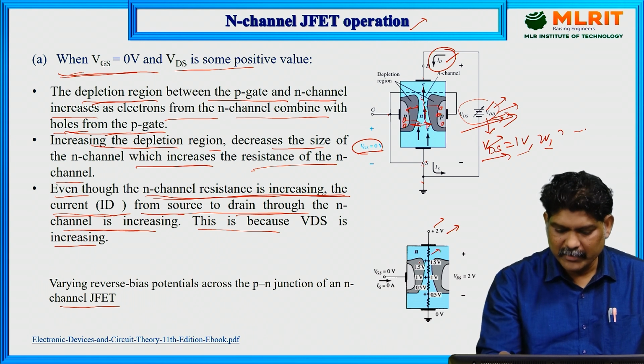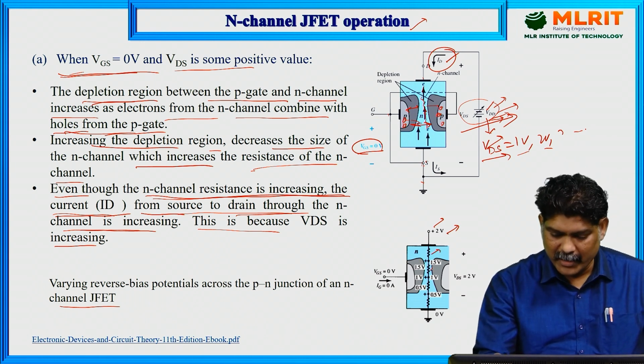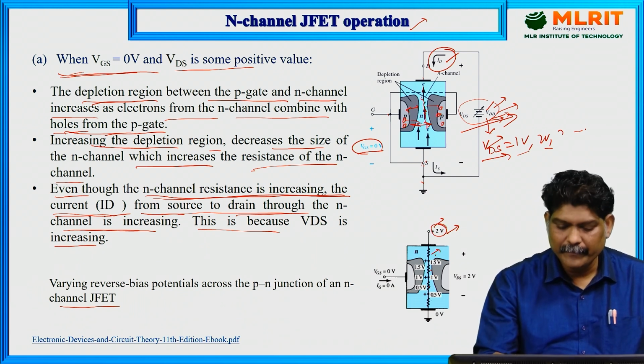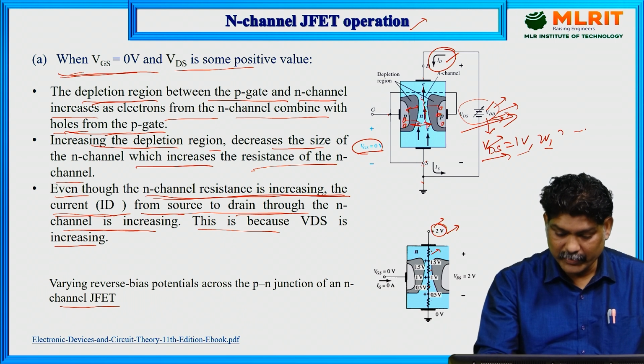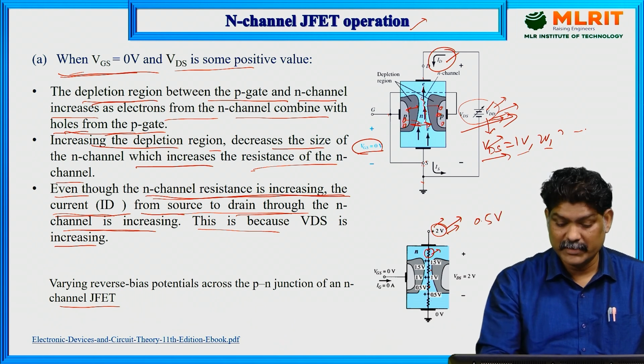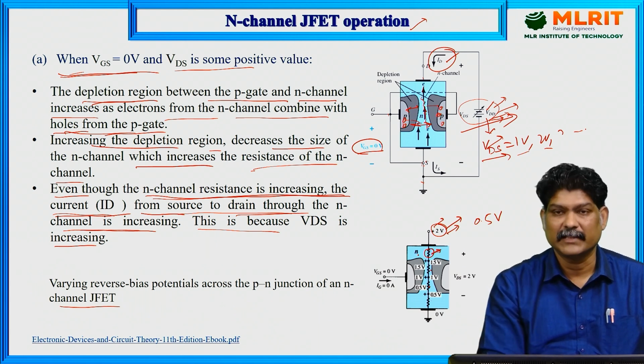So there is a series connection of 4 resistors, R1, R2, R3, R4, let us say, and these 2 volts will be divided. So at resistor 1, what will be the drop? Because 4 resistors are there, and we are giving 2 volts, obviously 0.5 volts drop across this first resistor. All resistors are equal here. So here 0.5 drop will be across the first resistor.